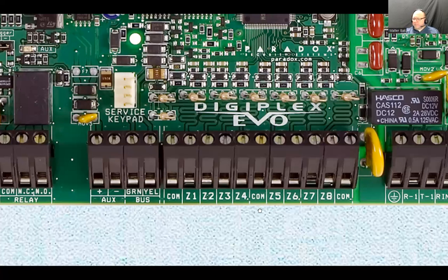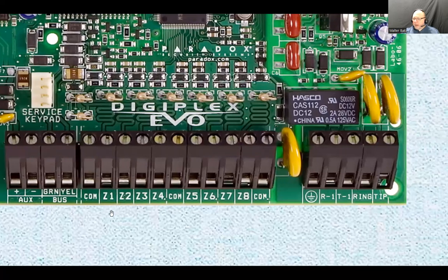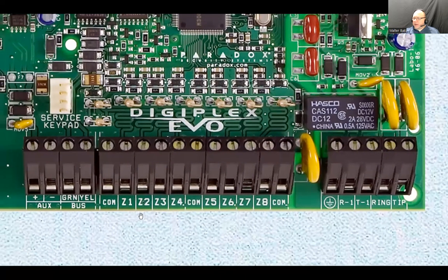Now here's another area, and you can see those Z terminals. These are the zones: zone 1, zone 2, zone 3, zone 4, 5, 6, 7, and 8. This board is capable of handling 8 zones. What is a zone? A zone is a contact point. It can be programmed as normally open or normally closed. If the system sees a connection, if you just run a wire between here and here, you're going to close the zone, and the system is going to be at ease.